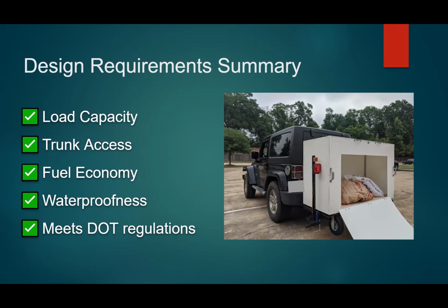Sounds good. On that point, it was very hard to find information on this type of thing, because of course it doesn't have its own axle. So we did a DOT light kit, so anything hanging off the back of your car is marked off. Not only that, but it has blinkers and running lights. We also treated it like a trailer that you would have for a boat. Another thing we did not mention that we added is eye bolts in the back of the enclosure itself, and those are safety chained to the back of the vehicle. That would be another safety. Ideally, we also wanted pins on the guidepost that would also fasten the enclosure to the guidepost.